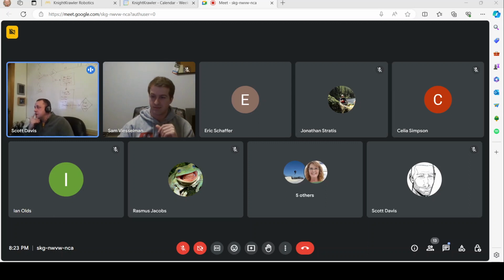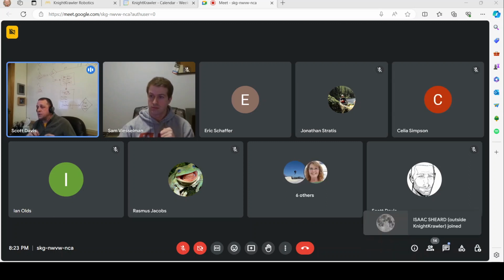Those are the cameras that we're using, the ArduCam, the 120 frames per second mono global shutter. They're black and white, so you can't do game element detection with them. You can only do April tags with them. We're also running them on an Orange Pi 5, which apparently has better throughput and processing power. We have 2 cameras, but we're only using one of them for April tags right now.